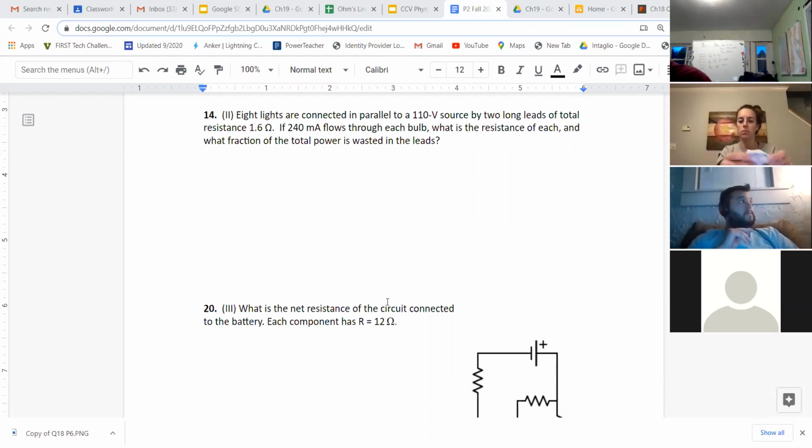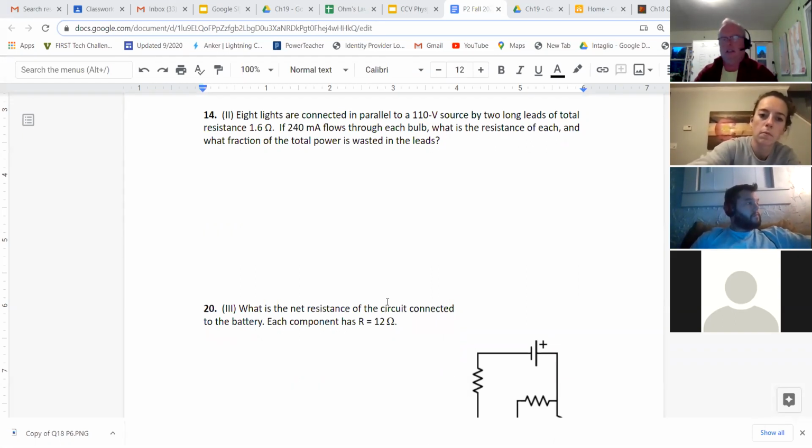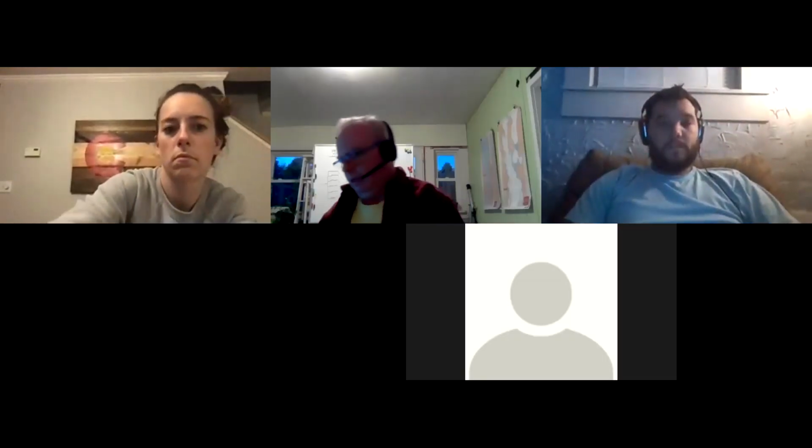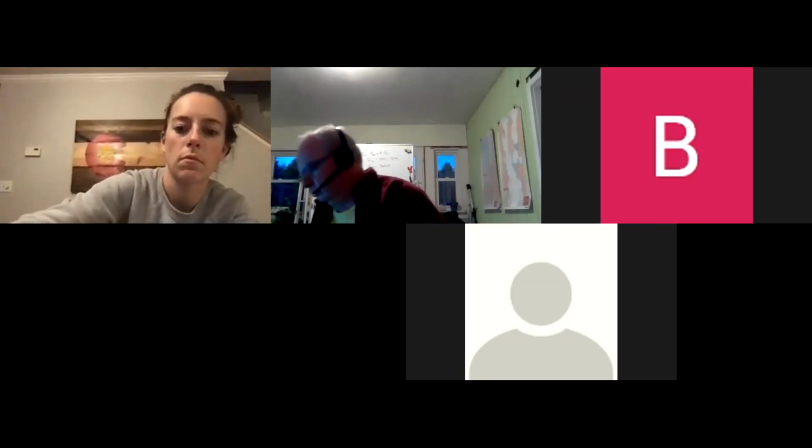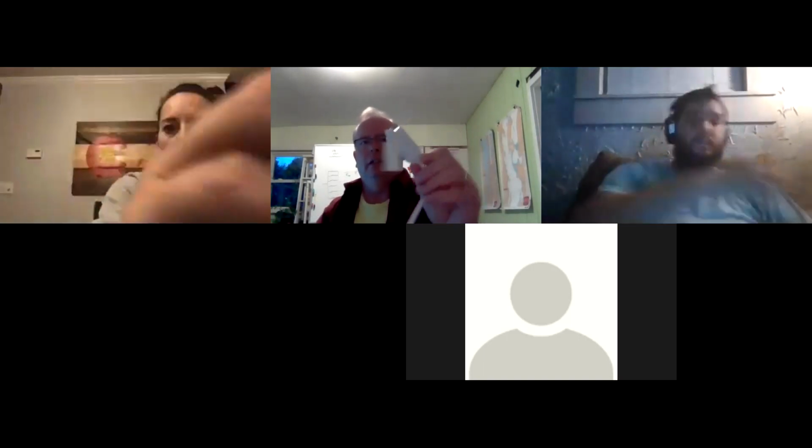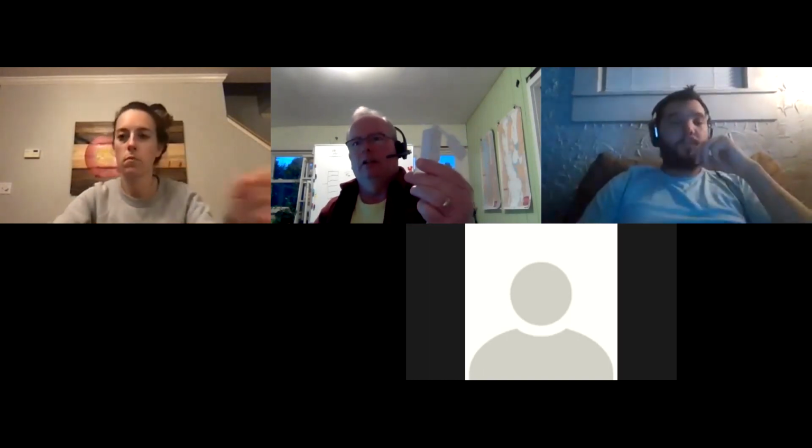Actually, I have an extension cord in here. That would be good to contrast. So I'm going to stop my share here for a second. Okay. So here's the extension cord that I happen to have. It doesn't have a grounding hole in it. That's a problem. So I can't really plug very much into it besides like a cell phone charger or a lamp. But also you can see the thickness. This is really small.